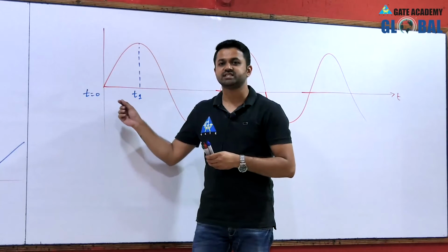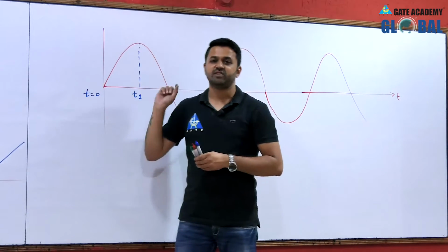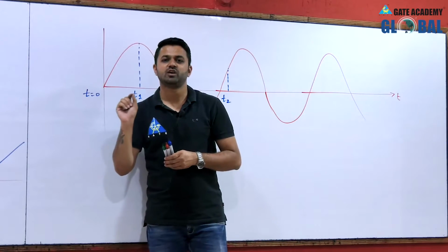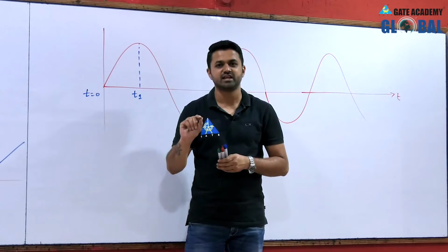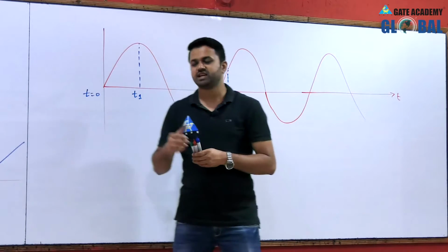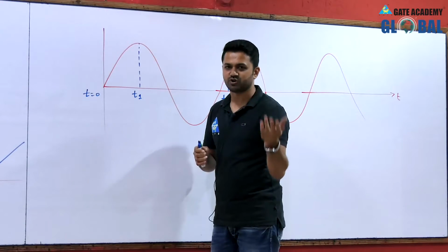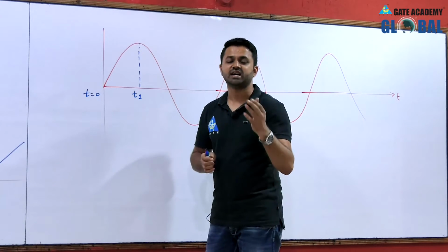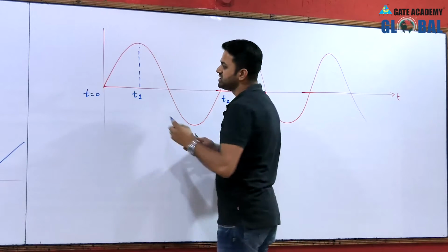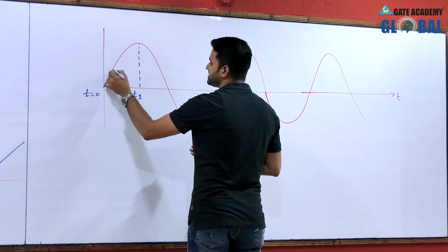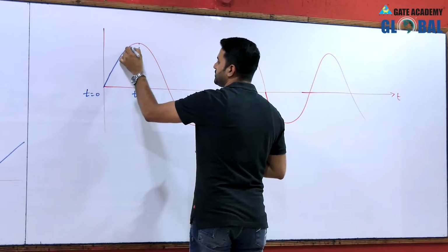When the input has positive voltage, that means greater than 0, then the potential at the P side is higher than the potential of the N side, then the diode is forward biased, that means short circuited, and the capacitor starts charging with the input value. So the capacitor starts charging to the input value.